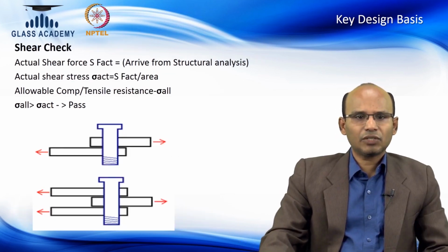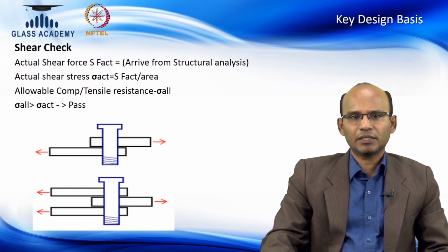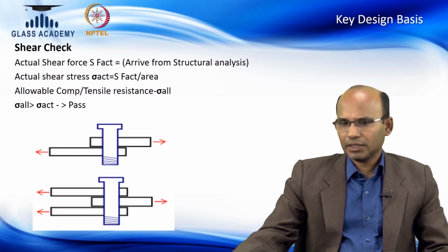Shear check is generally for connections and brackets, where large loads are transferred into a small component, and this kind of shear stress is critical. This is especially critical if using aluminum brackets. Aluminum brackets have slightly lower bearing stress and bending stress compared to steel. So this checking is critical for facade and glazing applications.